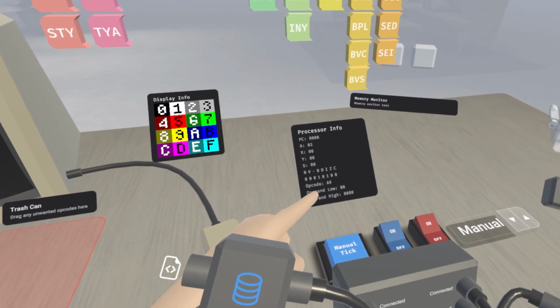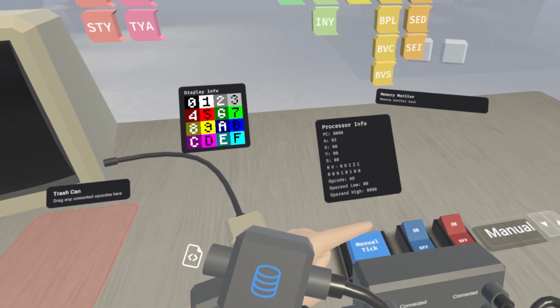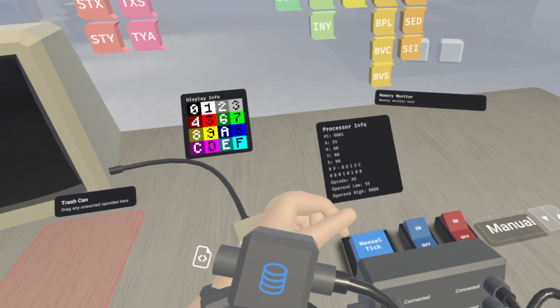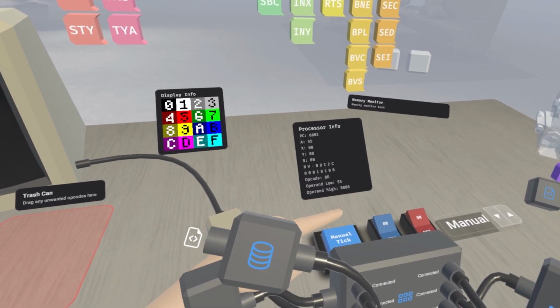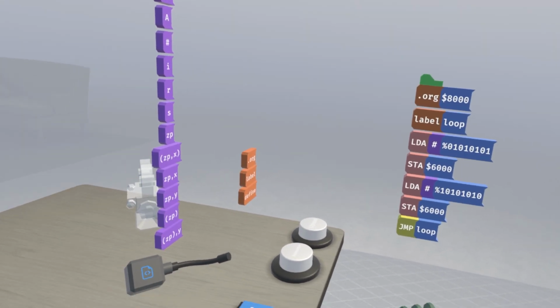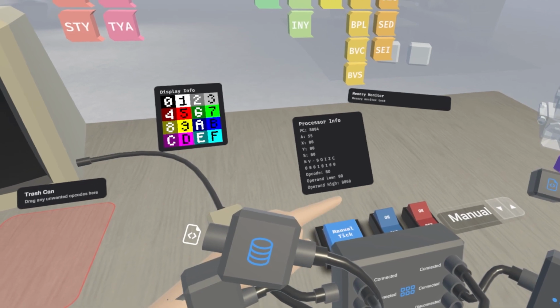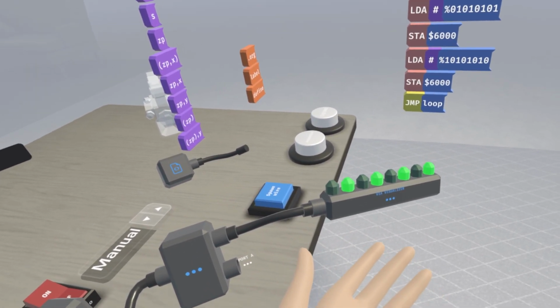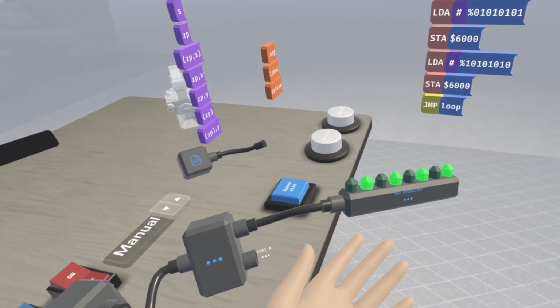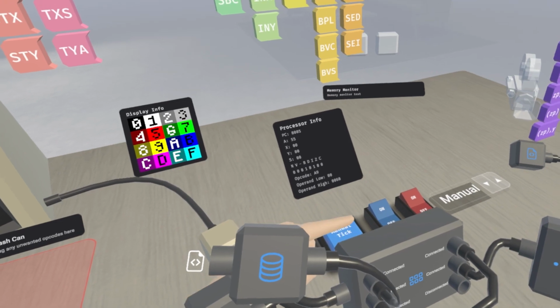So our first command is going to be A9, which makes sense because we're loading A. And then 55 is our operand. Then 8D is for store A. 00 and then 60 should come afterward. And it does, look at that. Our versatile interface adapter visualizer right here lights up with that marquee effect. Let's go for a couple more ticks.